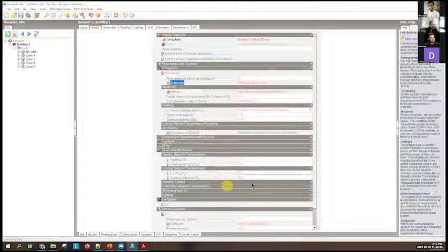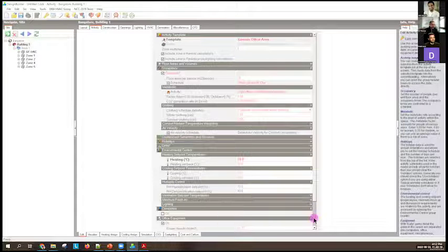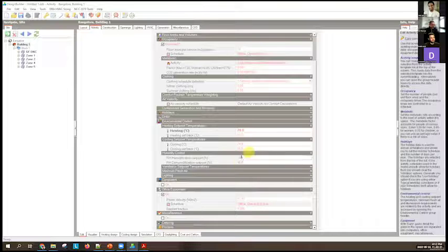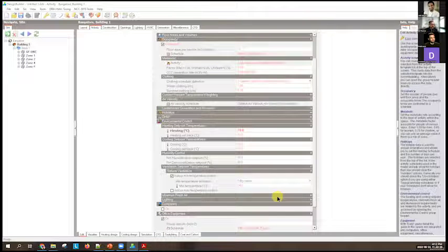There are some heating and cooling set points. So if we say that heating is only up to 20 degrees, and cooling is up to 24, then you can put that in there. If you want humidity control in your air conditioning system, you can put the correct numbers in there. There's something here called ventilation set point. I'd like you to remove that.